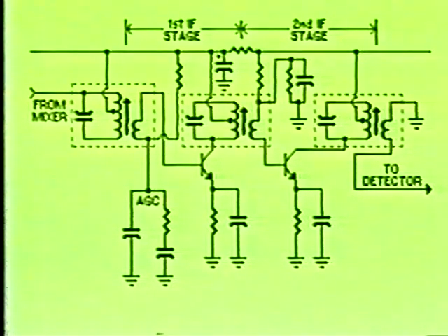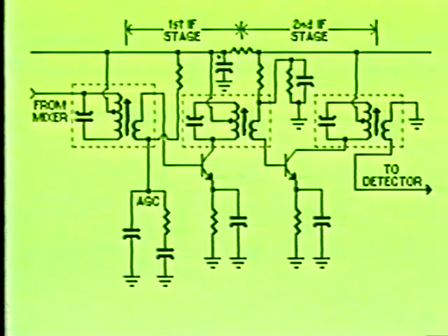Many of today's modern receivers use components other than LC tank circuits to provide the intermediate frequency selectivity. Crystal filters are becoming increasingly more popular. This is due to the fact that the crystal filter has a typical Q factor of nearly 1,000. The primary difference between the intermediate frequency amplifier stage and the preceding stages is that the IF amplifier does not require tracking, since it is preset to a defined frequency limit and will remain tuned to this frequency regardless of the input RF signal. Since the IF amplifier stage operates in the low radio frequency spectrum, there are many transistor amplifier circuits which may be used to perform this function.